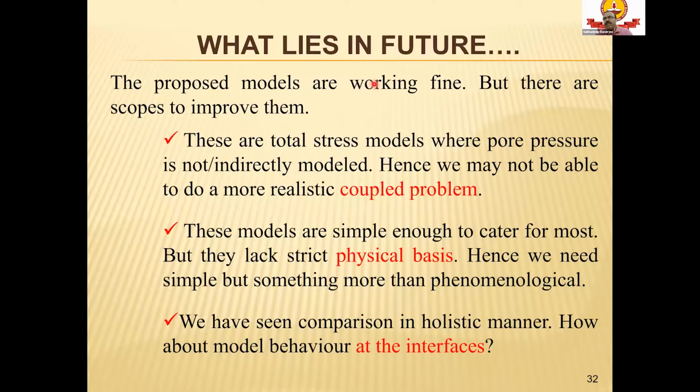So to summarize, what lies in the future? In fact, if you ask me, the proposed models are working fine, but there is scope to improve them. This is a total stress model essentially, where pore pressures are modeled only indirectly. Hence, we may not be able to do a more realistic coupled analysis, which is required for most advanced soil structure interaction problems. These models are simple enough to cater to most needs, but they lack strict physical basis.